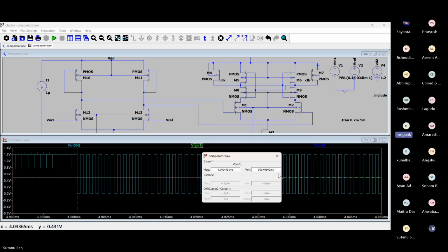But then if you go further, if you want to have say a 12-bit ADC, then it is going to be 2 to the power of 12 levels. And now you need to resolve 0.25 millivolt. So depending upon the application, you may require higher resolution comparators, and accordingly, we need to decide whether we need a preamplifier or not. What should be the gain of that preamplifier? And these things will also decide the speed, because if you're going for higher resolution, speed may also be limited,